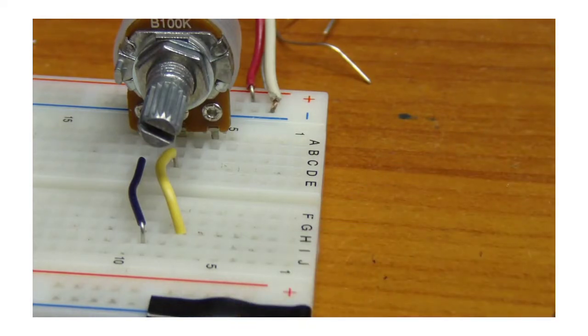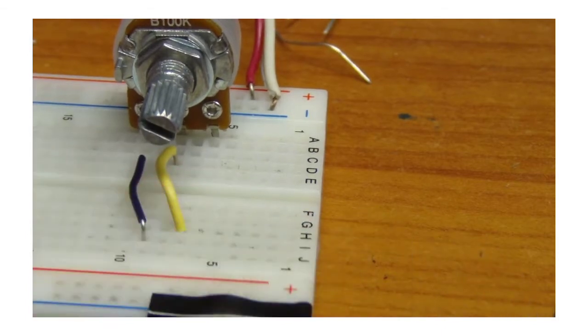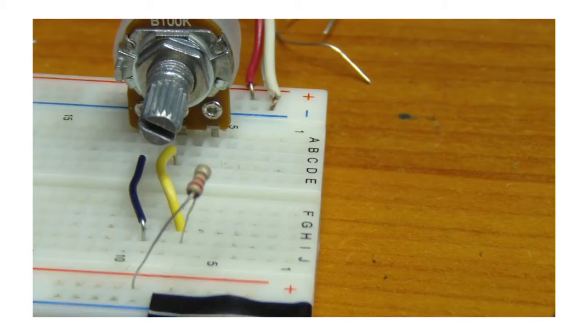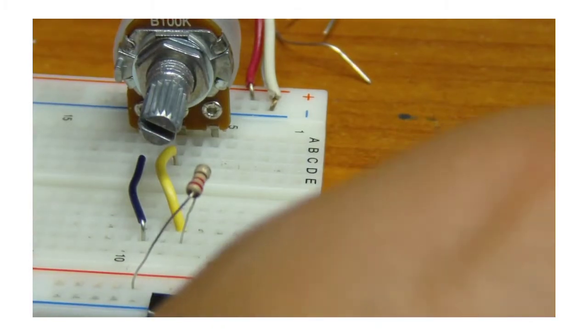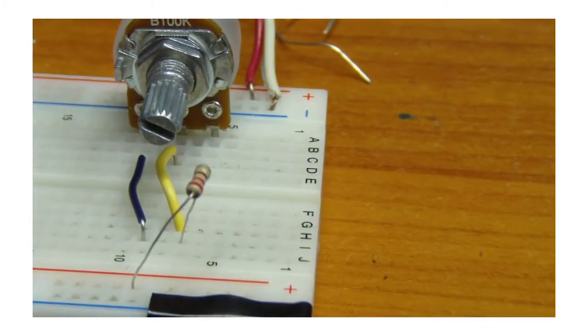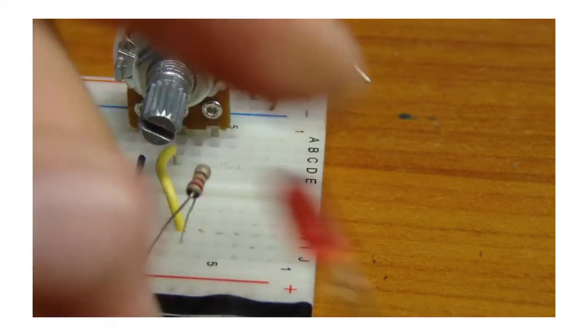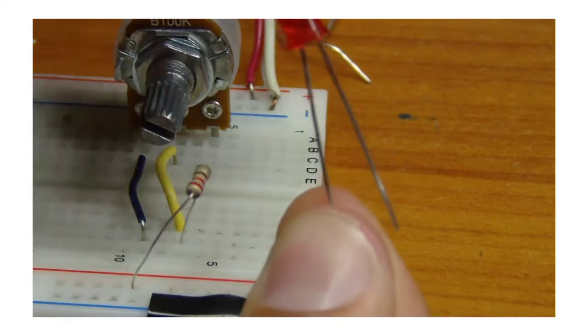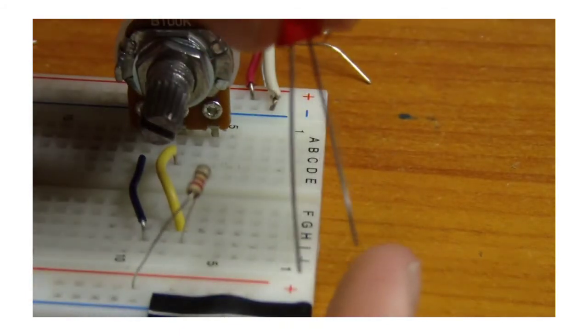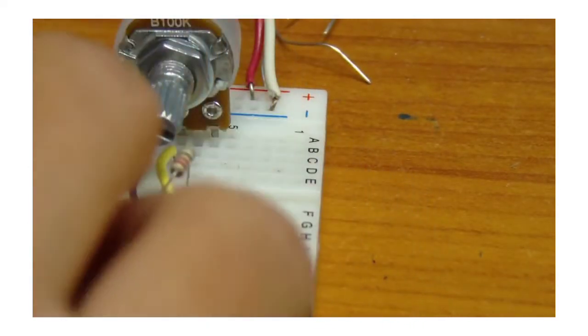And the next thing you want to do is use your 220 ohm resistor right here. Plug it into the middle prong. Well, I have them connected by wires to the plus 5 voltage. And then the next thing you do is just remember, that's plus, so you're going to be hooking up the small or the shorter lead into the negative terminal. So let's do that.